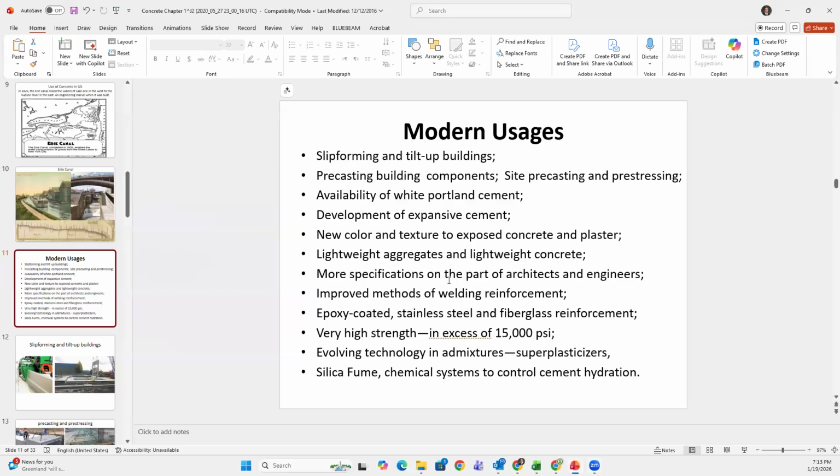Thanks to CNC rigid foam detailing, they can just CNC the negative and set it inside the form, and you've got birds flying and everything. The CNC machines just do all the artwork. Well, somebody does the artwork. They CNC the mold, and then they set it on the inside of the form. Correct. But you need to have a proper concrete, so all of a sudden you don't have a big rock in the middle of the bird. So you have to know your mix if you're venturing that far.